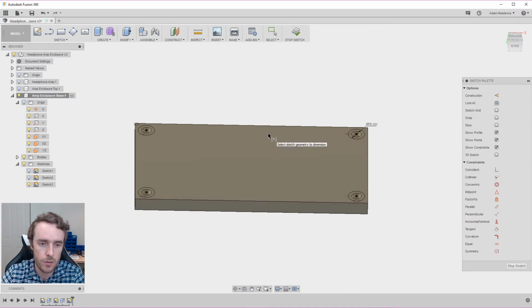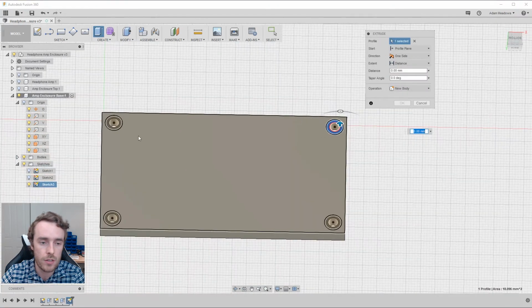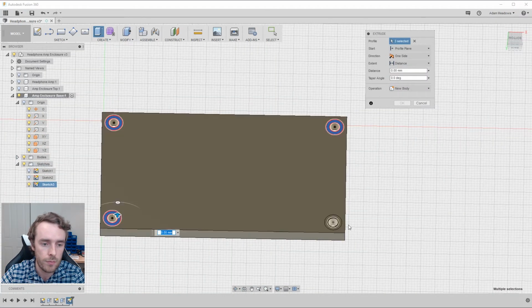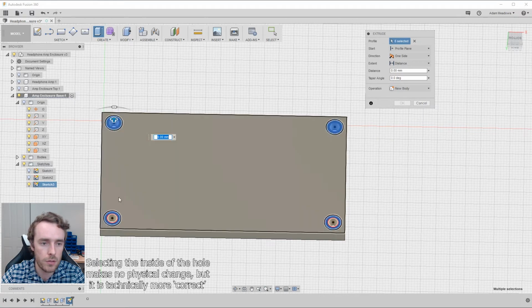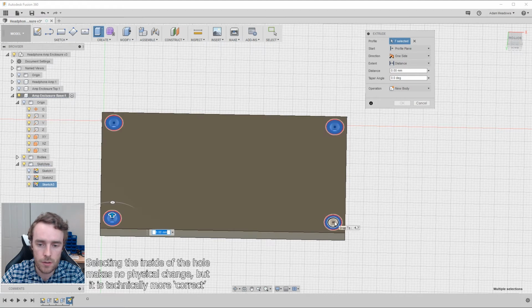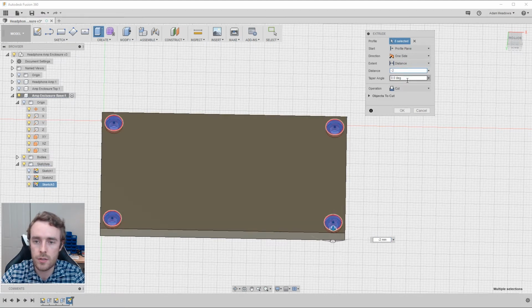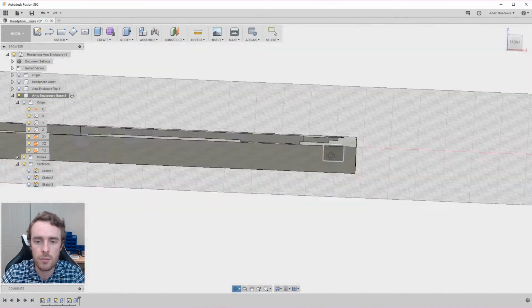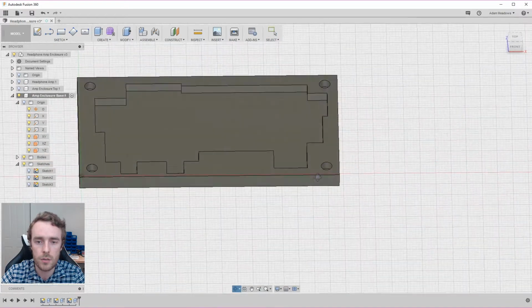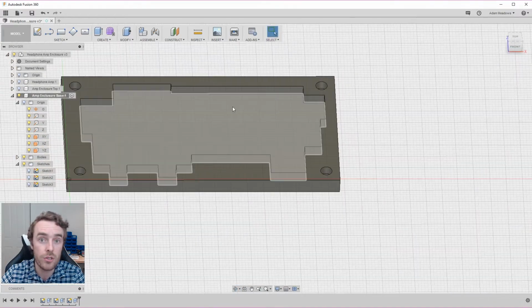We're going to extrude that downwards, so this is going to be a cut operation. Technically we want all of it like so. We're going to be going down 2 millimeters. Make sure it's set to cut, no taper, objects to cut, just the one body, okay. So now that slight counterbore has given us somewhere for the head of the screw to sit.